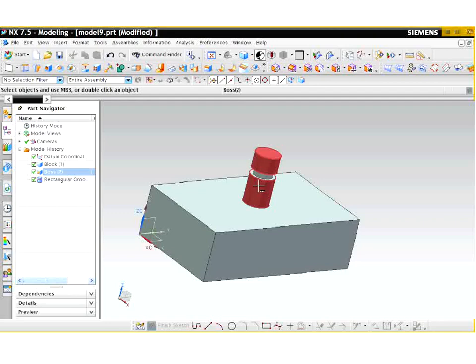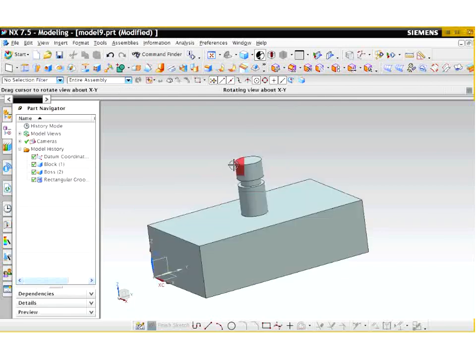So what I'm going to want you to do now is practice. I want you to look at section 6.7. Apply some of these techniques we used, our extrude function. We're going to practice combining two different sketches together, and we're going to practice making holes in these sketches in order to create a door hinge. And we'll practice this in class. So I'll be continuing on in my next lectures over Chapter 7.